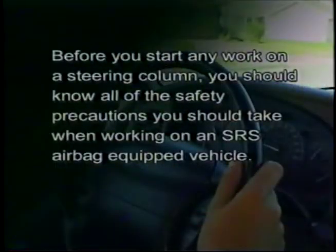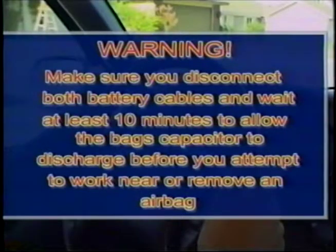Before you start any work on a steering column, you should know all of the safety precautions you should take when working on an SRS airbag-equipped vehicle. Make sure you disconnect both battery cables and wait at least 10 minutes to allow the airbag's capacitor to discharge before you attempt to work near or remove an airbag.